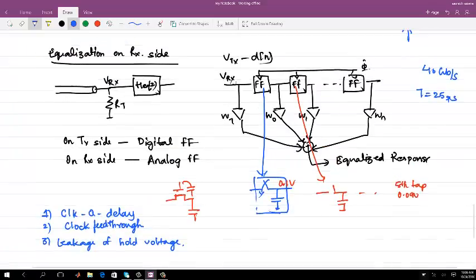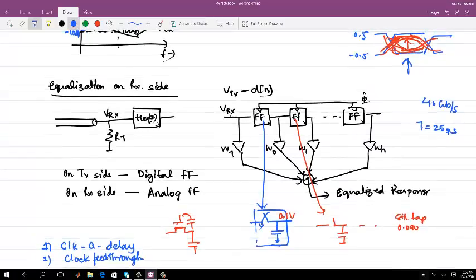So one other thing which you can say is, okay, if I am having these flip-flops, I can use buffers in between to drive the next one. Now, if you use a buffer in between, you added a delay from clock to Q. What power consumption is the buffer going to have? Then that will come into question.